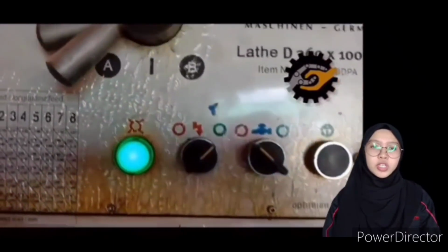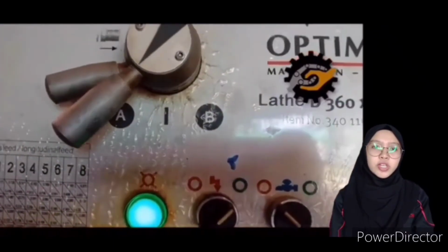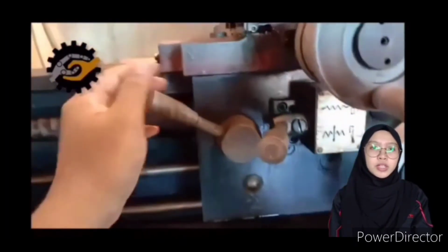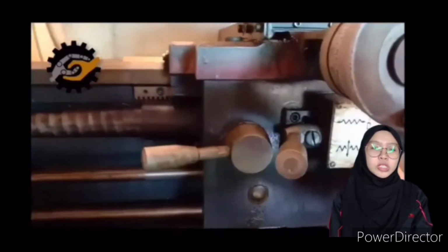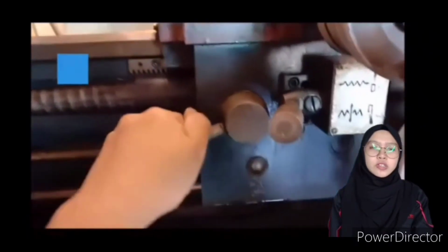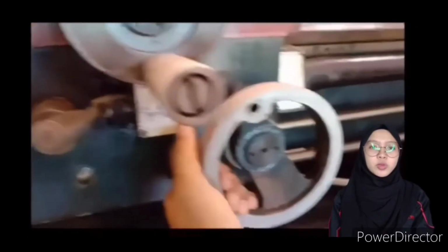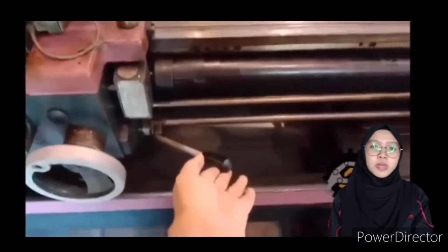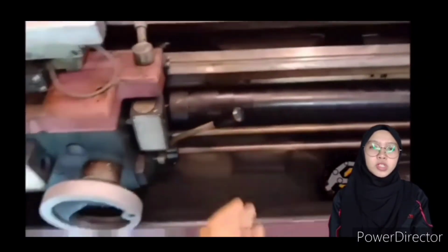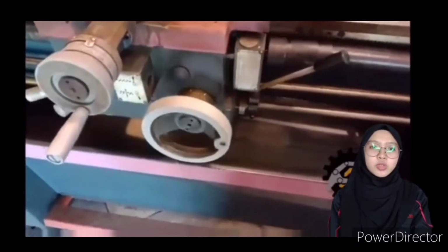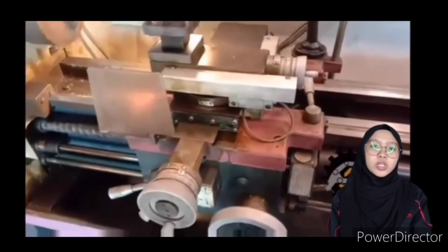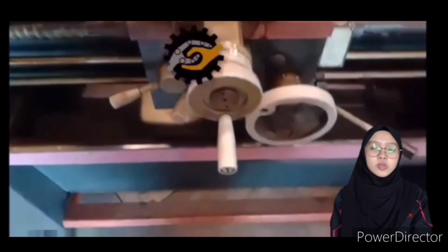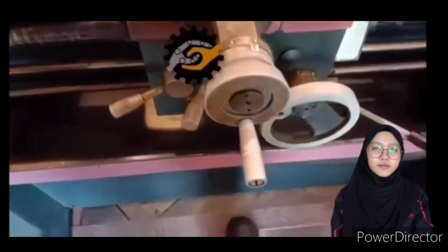After that, we need to take a look at our rotating workpiece to see whether it is suitable for the cutting. Push on the pedal that is used to hold the tool bit so that we can adjust the distance between the rotating workpiece and the tool bit. After that, push the main pedal to turn on the lathe machine. We can see our machine rotate counterclockwise at regular speed. If we want to stop our machine, we just need to step on the brake.